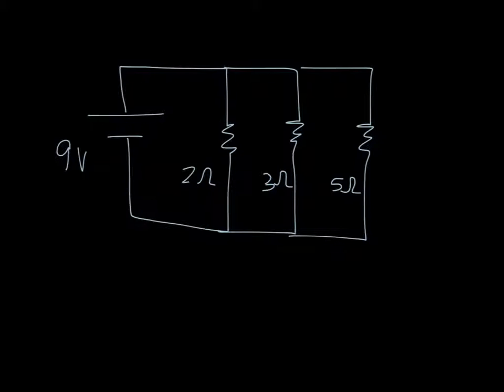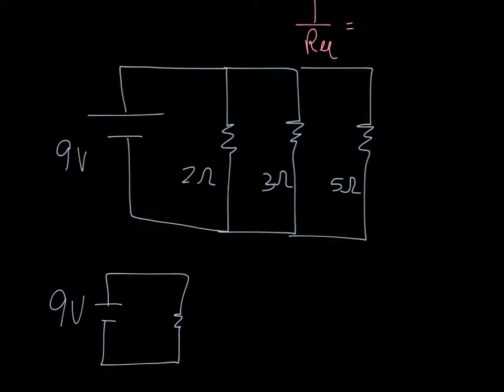So I need to come up with an equivalent resistance again. I need to figure out what should go right there for this one resistor that will replace the 3 above. Tom, tell me how I start this. You would add, you do 1 over R for each, so you add all of them, and then you would do the inverse of the final answer. Okay, so I have to use my reciprocal sums. Tom recognizes that it's 1 over R. So when I add together those 3 fractions, I have to take the reciprocal or the inverse of that answer.